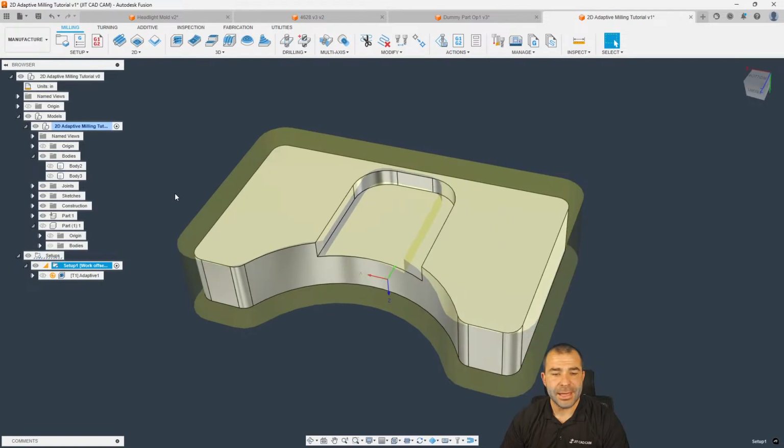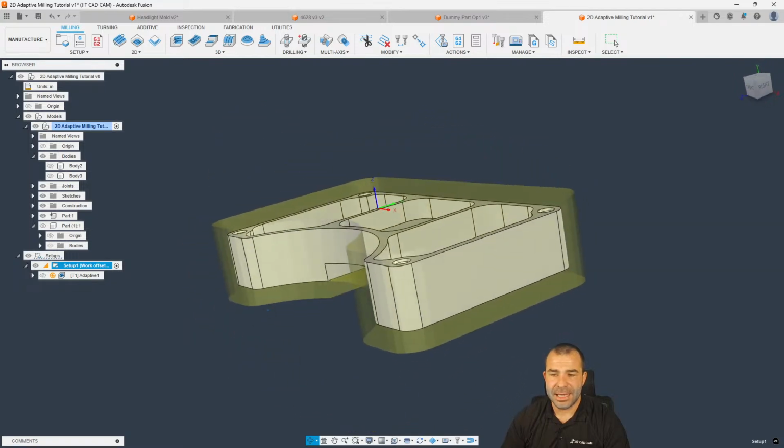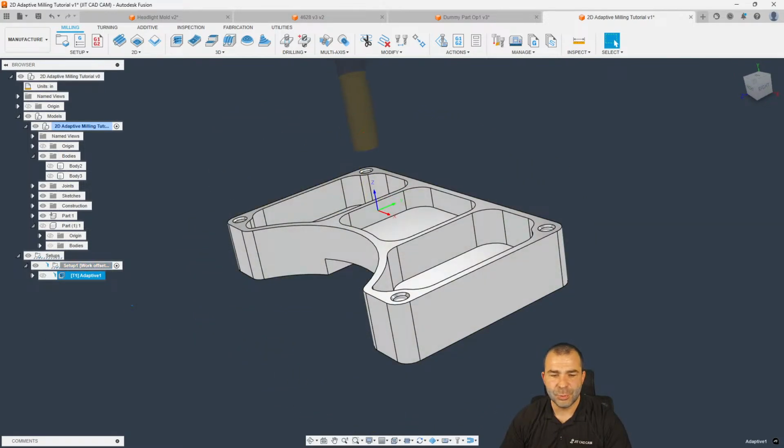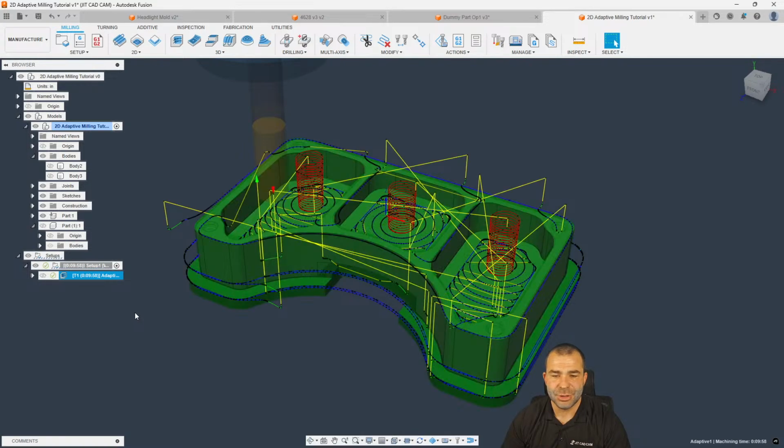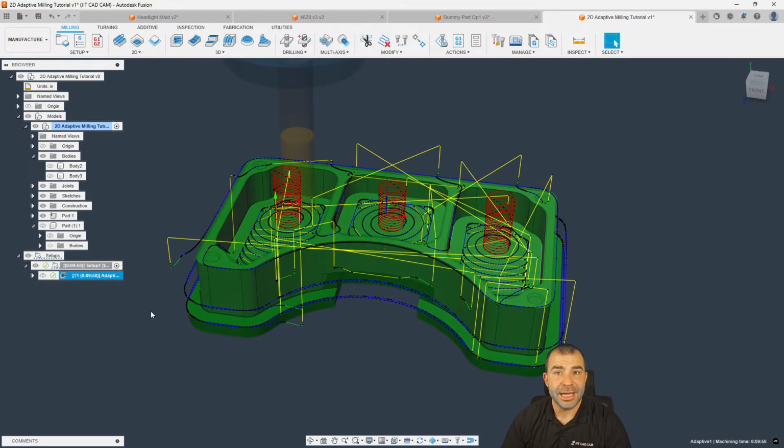So if I go back into Manufacturing, again, we regenerate our toolpath. What's going to happen is Fusion is looking for anywhere it can machine versus where the actual physical finished model is. Again, same concept, whether it was large scale, small scale, scaling up a part, scaling down. I used to do vacuum form fixtures. I mean, we had to put shrink on parts because when they cool, they would get smaller, things like that. Deep Thinker, does that kind of answer your question?